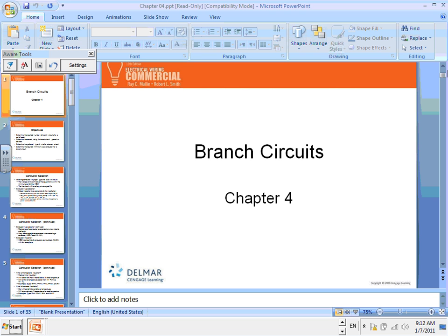What I didn't do is they choose what part of it is nonlinear, so you don't derate the neutral. What we did, guys, is we said we're not going to derate the neutral anyway. So if that's bothering you here, this is just to calculate the neutral, to tell you, hey, you have this amount of nonlinear load, meaning you don't need to derate it for the neutral. That's the only reason why they have this.